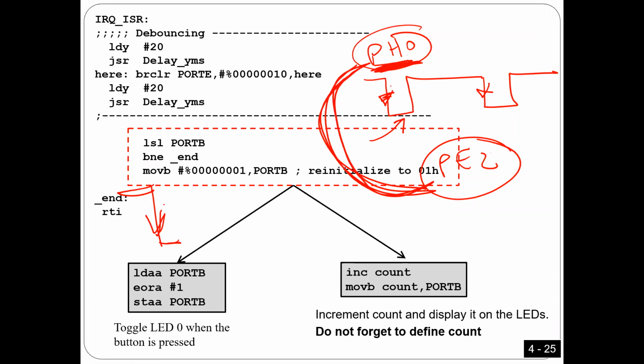The reason I use BH only in this program is that in this program, every time you push a button, I want to trigger IRQ interrupt. I want to do something every time I press a button. And what I want to do here, I'm going to put it in IRQ. So when I press a button, I'm going to trigger IRQ interrupt, and then I'm going to write here shift LED. That's what I want to do here. So it depends on where the signal is coming from. It's not always that you have to wire it. No, the answer is no. Only in this program. Is that okay?